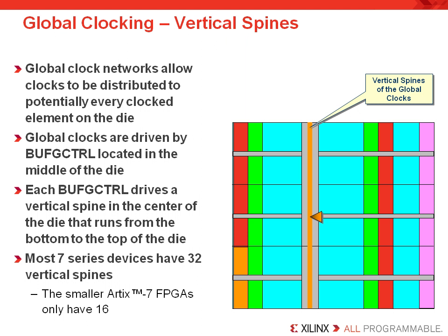The 7 series has a large global clock network that provides for the distribution of up to 32 different global clock signals across the entire FPGA. These reside in the center of the device. The 32 BUFGs each drive one vertical spine of the global clock routing resources. The output of each BUFG can drive onto a BUFH to get to a CLB.